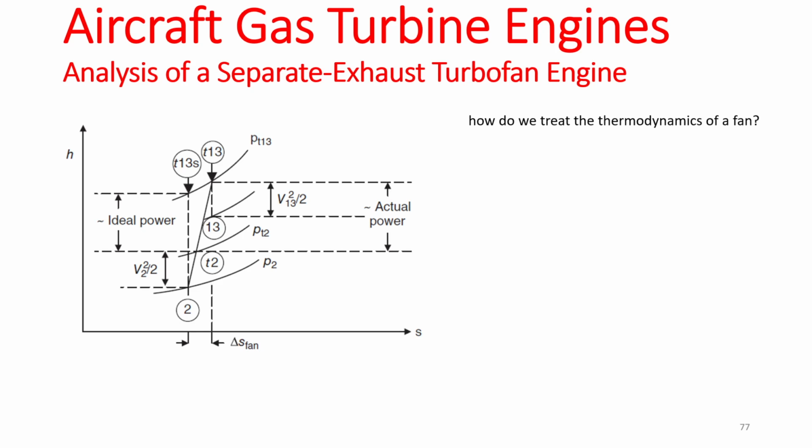I would say it's similar to the exhaust nozzle here. It's like what provides the thrust that increases the speed. But your CP doesn't change, like the nozzle has a different CP from the inlet. You could count coming into the fan as like inlet. You could count exiting the fan as an exhaust nozzle, if you go from the front. It depends if you're trying to do the equations for entering the fan or exiting the fan. That's what I'm trying to say.